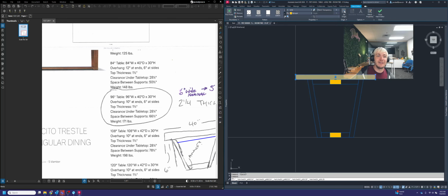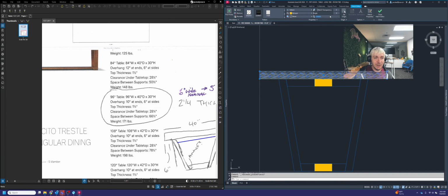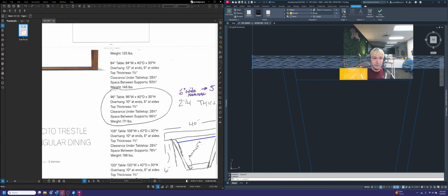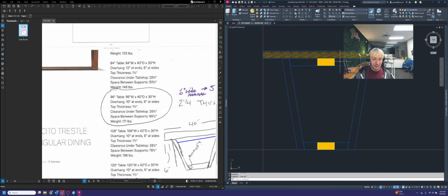If you know what that hatching needs to be, for instance, in this case, I know this table is actually being made out of solid lumber, so I'm going to set that to be Legno 1, which is essentially on-site standard for solid lumber. Over here, there's a setting for layer or hatch scale. If you adjust this, you can change how much hatching is shown. When it was set to 1, by default, it looked very crammed. So what I'm going to do is set this to maybe 3 or 4. That way it's not so crammed and congested.